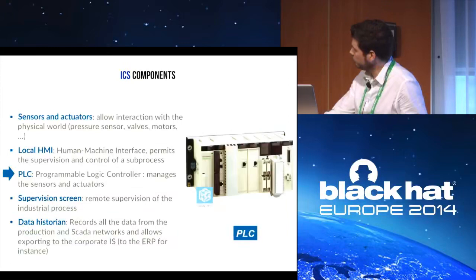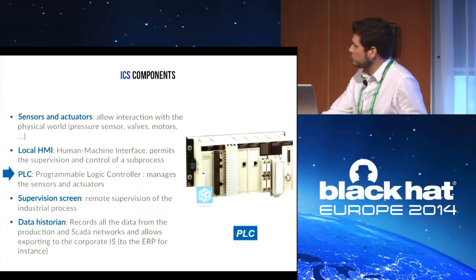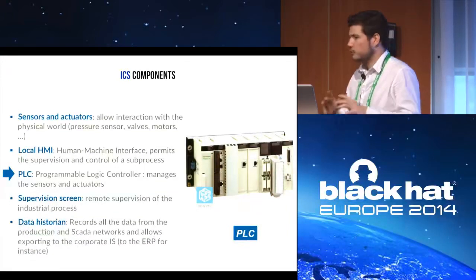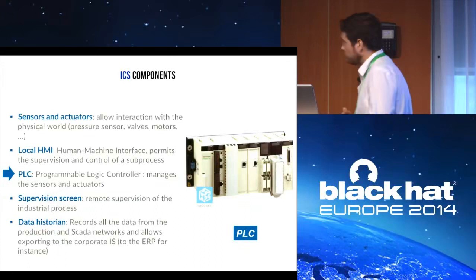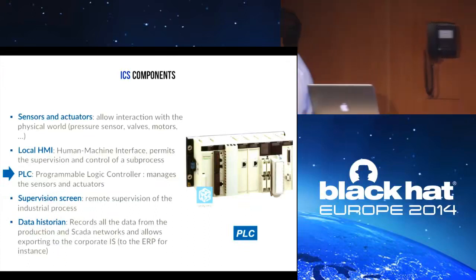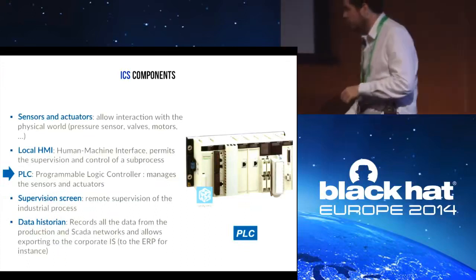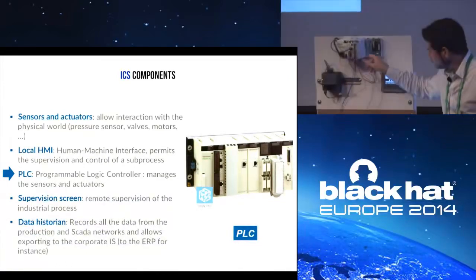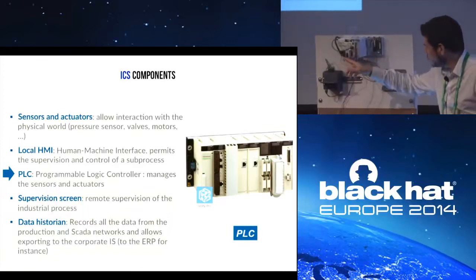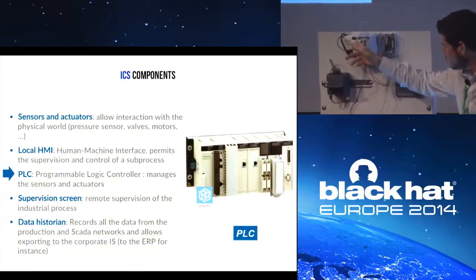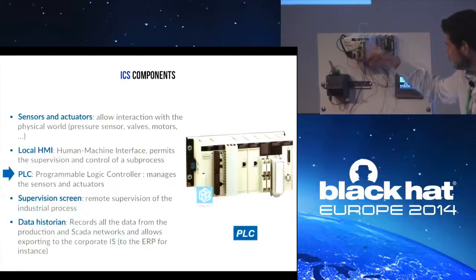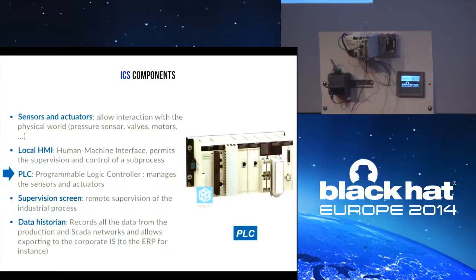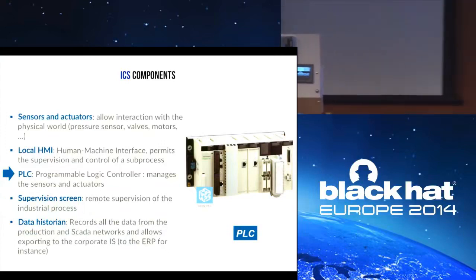So that's quite important. PLCs, which are the subject of today, means programmable logic controller. It manages all the sensors and the actuators. For example, on the picture, it's also a PLC from Schneider. I'll come back to it later, but just quickly, you can see that there is the power. That's what we call the CPU, so it processes the information. And then we have an input-output card that allows interaction with the sensors and the actuators that I mentioned.